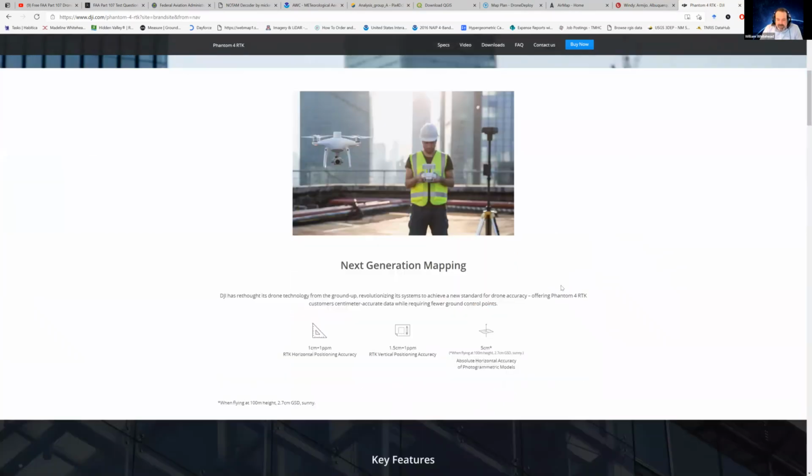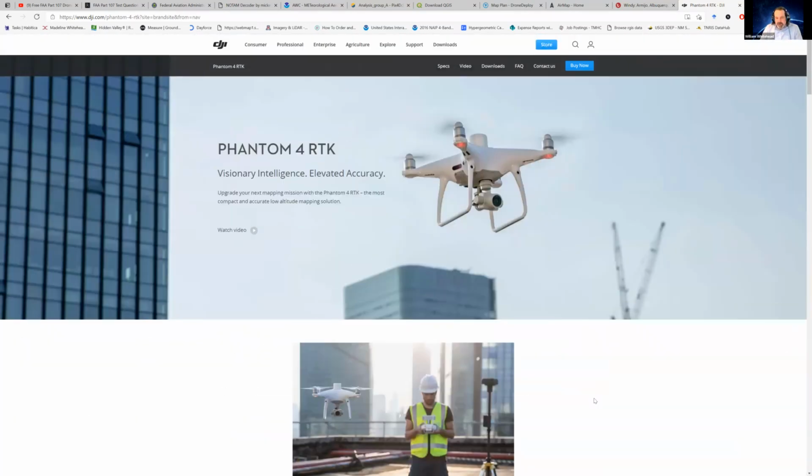And of course, what's really good is it collects all your ephemeris data, all the data around what the GPS heard when it snapped the photo. So then you can do post-processing kinematic correction of your data after you get the correction